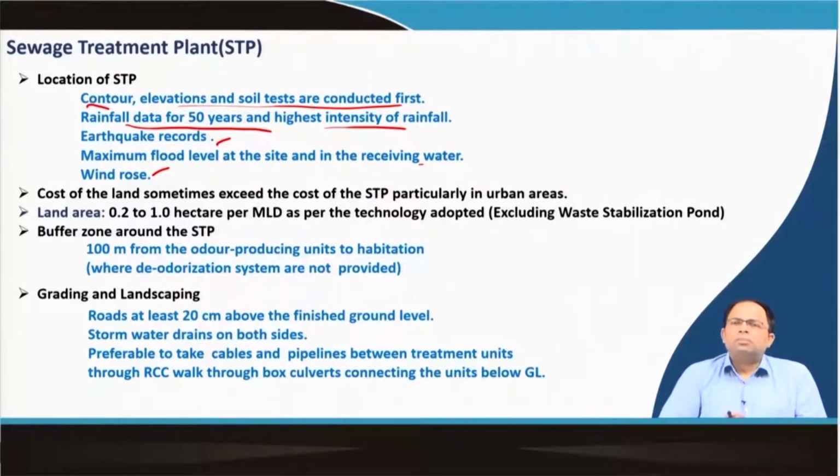If we have the sewage treatment plant far away, then automatically that means the sewage will first go there and again return from that plant. So, there we unnecessarily have to lay pipelines, and it will increase cost, right, and energy as well, because pumping energy would also be spent. So, it is better to have the sewage treatment plant in the urban area itself, right.